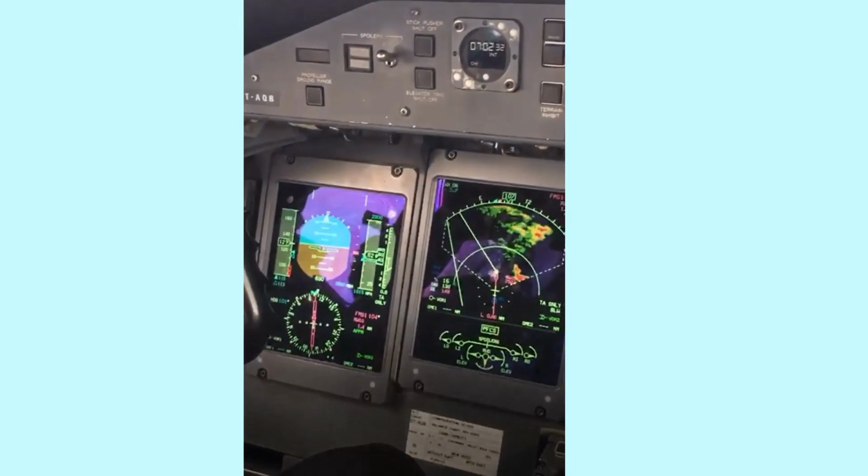And now you can see I am trying to keep, now the autopilot is not there, I'm hand flying the aircraft, and you can see that I will keep these black wing bars somewhere in between the horizon and the negative 2.5. So my eyes will be looking at this mostly because I'm assured that if I'm somewhere here, it means the rate of descent here will be around 600 to 800 feet per minute. I hope that is making sense.